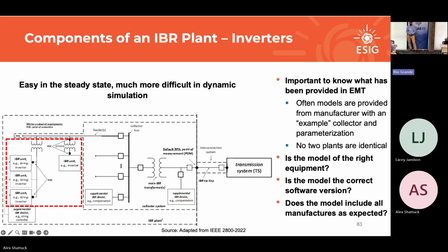The other things when you're getting inverters sound super simple, but these are mistakes that happen all of the time. Is it the right equipment? Is it the right manufacturer that you chose? If I know I'm working on a manufacturer A plant and I get a model from manufacturer B, I'm going to ask a follow-up question to see if this is what you meant to send me. In that type of situation, that's a little easier to catch.